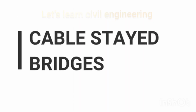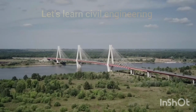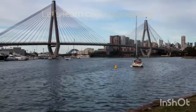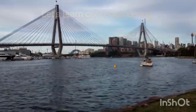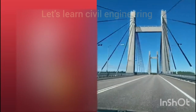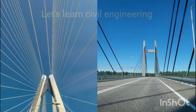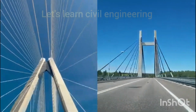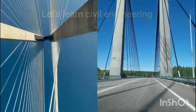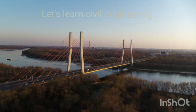Cable-stayed bridge. The use of cables as the primary load-carrying elements in bridge structures has proven very efficient, as the high strength-to-weight ratio of the cable material will decrease the escalation of the dead load otherwise related to longer spans. Due to the versatile nature of cable-stayed bridges, this type of bridge design is adopted for a variety of span lengths, from footbridges less than 50 m in length up to spans of more than 1000 m carrying traffic load. There are currently well over 1,000 cable-stayed bridges around the world.